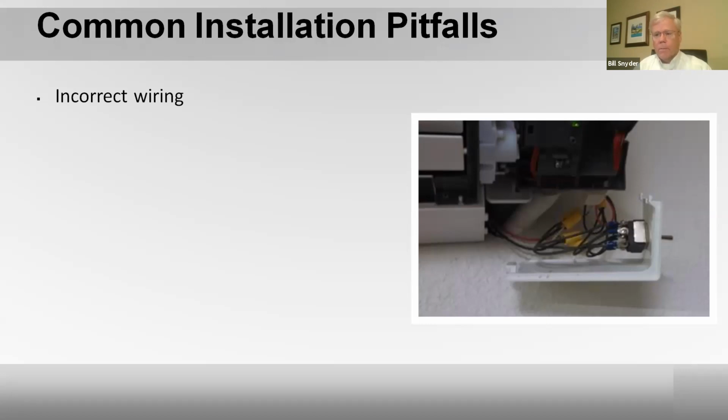And that is available. What we typically do is all of the indoor units are powered from the outdoor unit. So when you throw the disconnect on the outdoor unit, everything downstream of it is off. And that's usually acceptable in most areas. In some areas, your electrician may require a disconnect at the indoor unit. And in that case, you would use the approved Mitsubishi disconnect, not something like this.